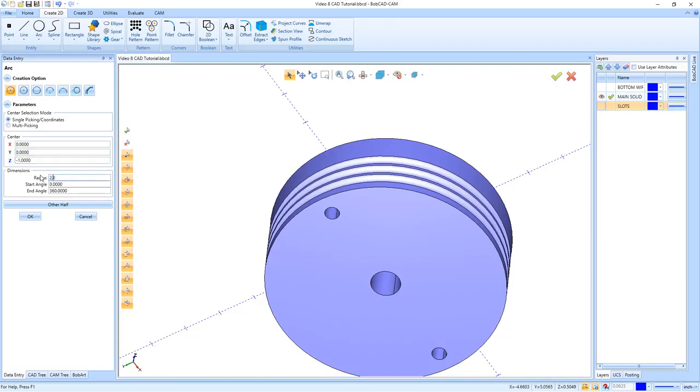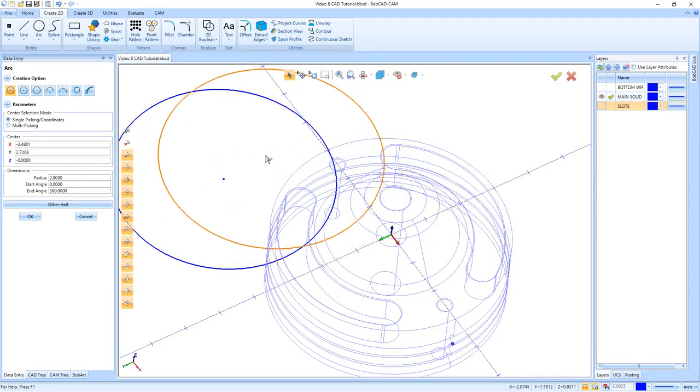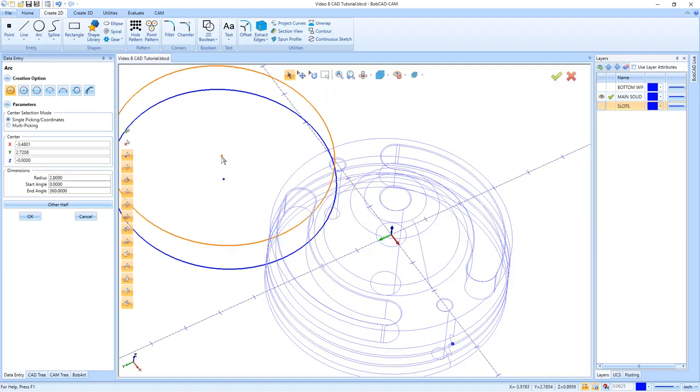Now you can't see what's happening right now, but if you click out of this box and you just click in here for a second, you can then hit the letter S. So when I hit the letter S, it hides the shading. But now since I clicked in the window, I have a preview. But you'll notice it's a darker color blue than anything else on the drawing. And the reason is because it's an editable feature right now.